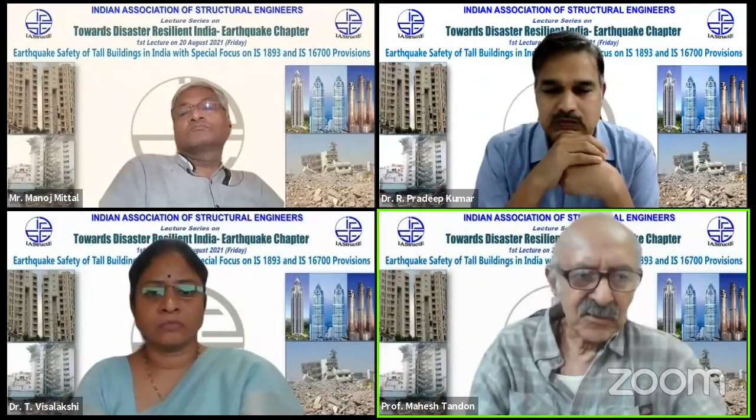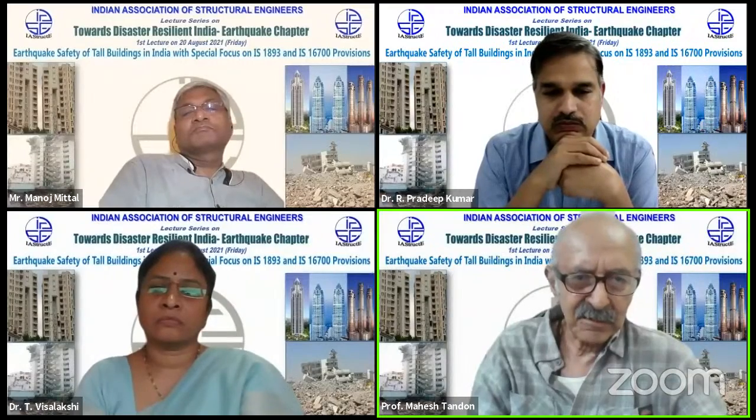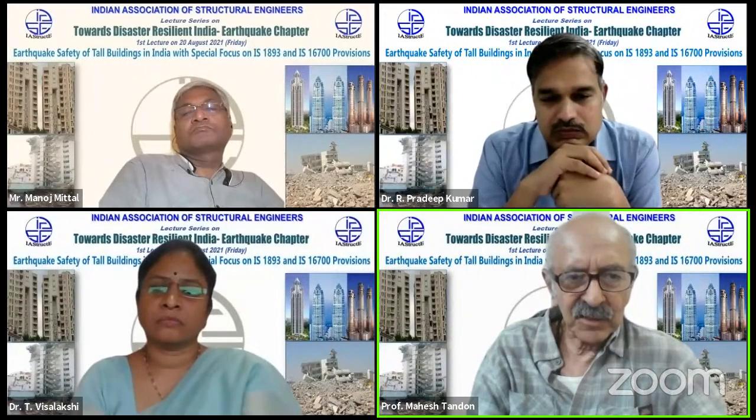So I think that's the answer. When you are doing deformations, there is no response reduction factor to be applied. You just do the normal analysis and find out the deformation.